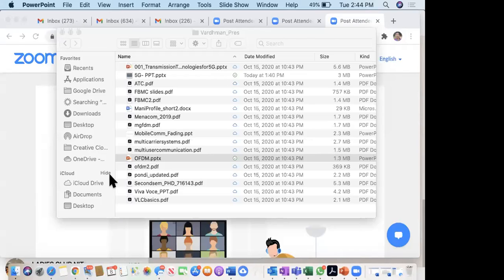So it is actually e power j 2 pi k n by N. Then how many subcarriers you are using and what is your data length must match. Otherwise, I cannot accommodate all my symbols into my FFT block. So that is always necessary.